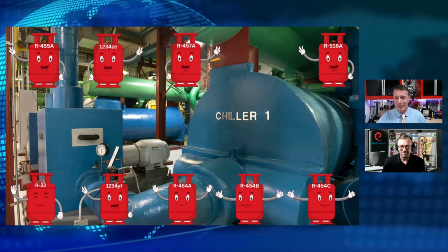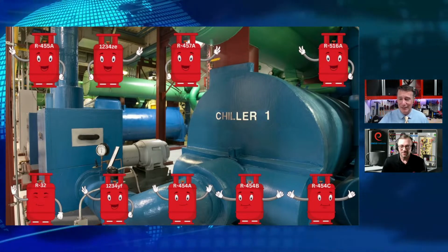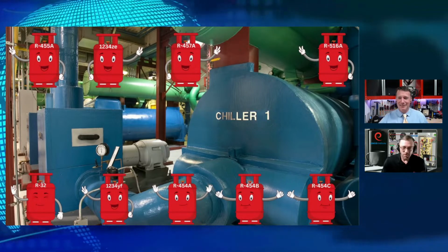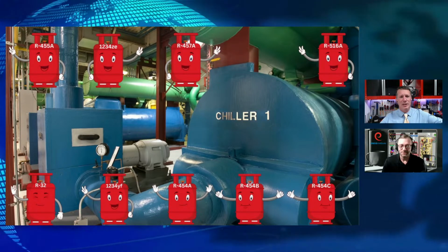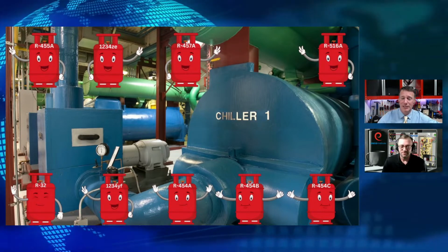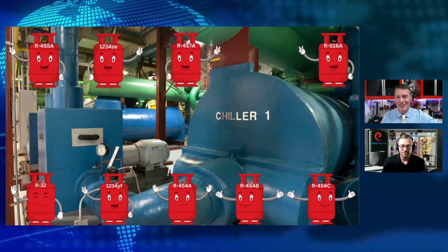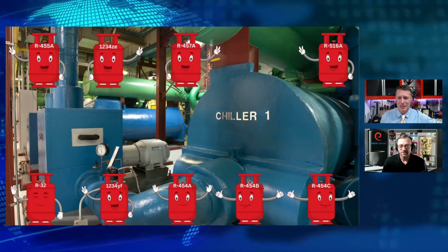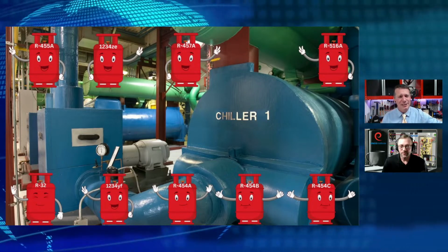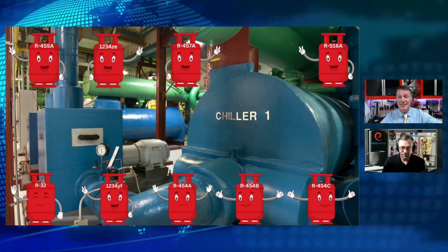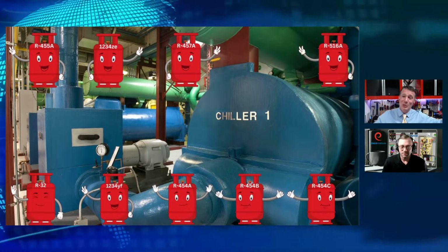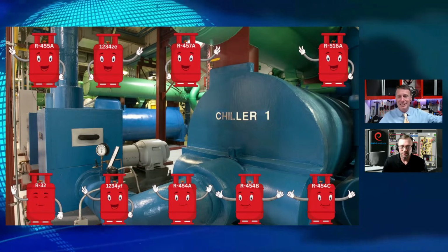A3 is what I consider a flammable refrigerant, which is a highly flammable refrigerant. Right. Mildly flammable, highly flammable, 2L and A3. Big difference between our mildly and our highly flammable stuff. And people will talk about that all the time going, I don't want to deal with highly flammable stuff. How many pounds of an A3 refrigerant do you have sitting underneath your seat in your van, right? Gasoline is an A3 refrigerant that we used back before we went to the CFCs as well.